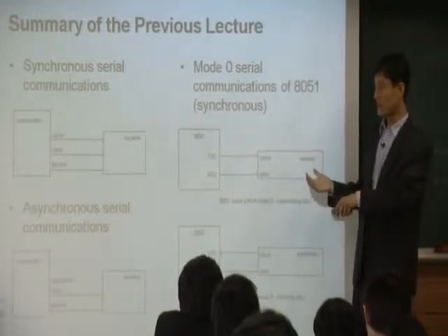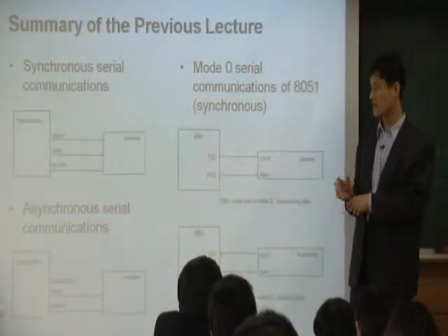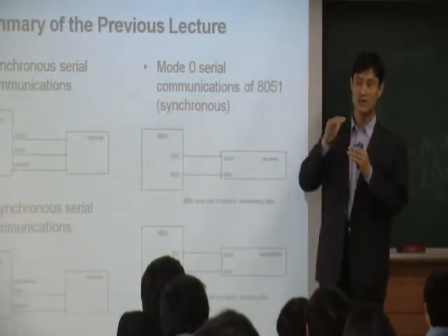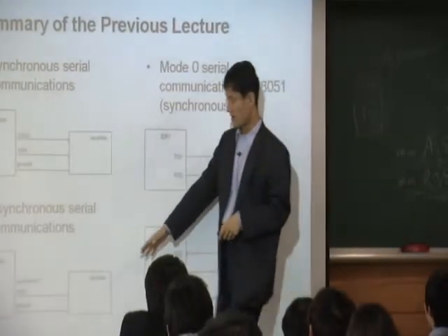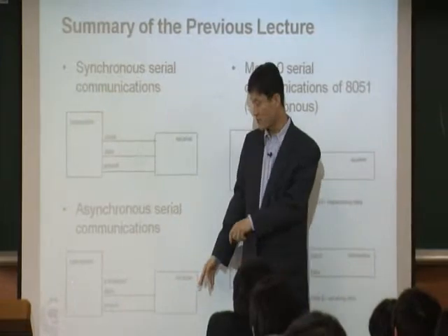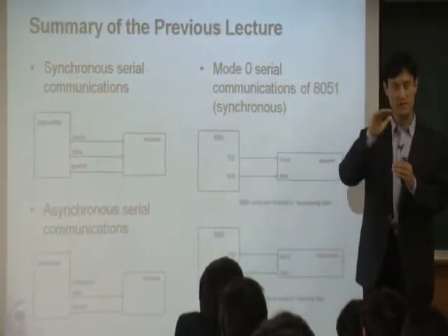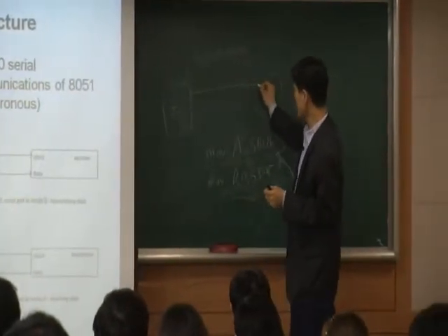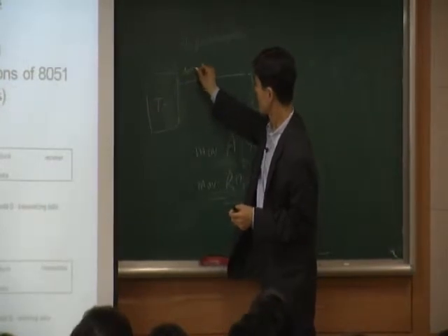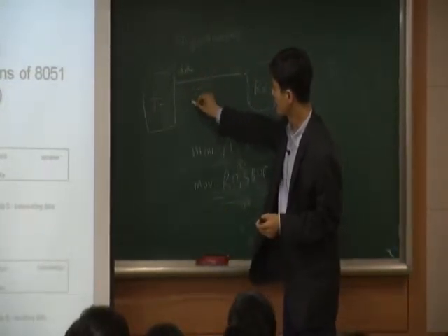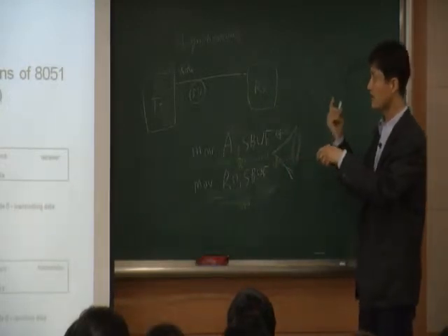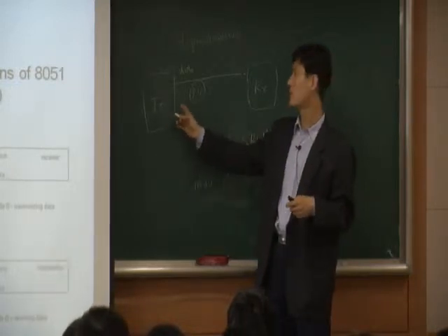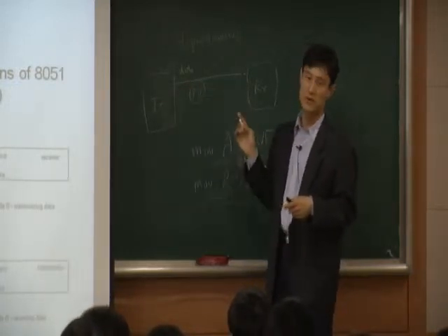A lot of the data pins in digital systems use active low, which means when you are idle, you have 5 volts. Same here. Over the data pin, if you are not transmitting anything, it is always 5 volts. So now, let's say this is the data pin here, and right now we have 5 volts on it, because the transmitter is doing nothing.